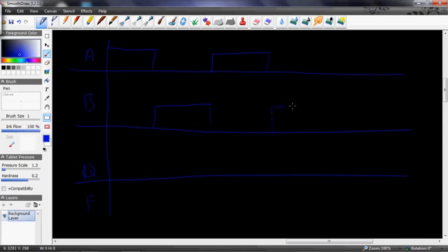And we'll say we're doing an adder. So at each point, say here, would be when the output would finally catch up. So I'll just draw these little dashed lines to show when the output would finally resemble. And this is the timing delay that's talked about in most basic logic classes. Okay, so then let's draw this output. 0 plus 1, well that's just a high. Now this is 1 plus 1, so this is always going to be high.